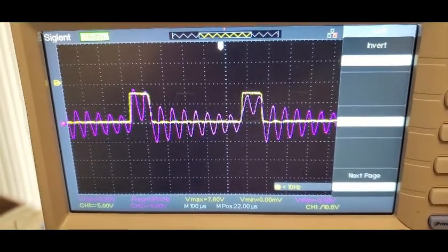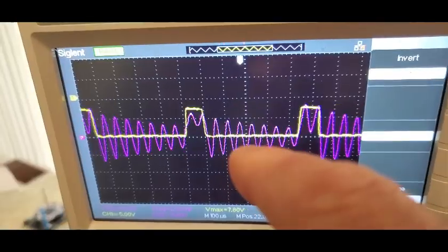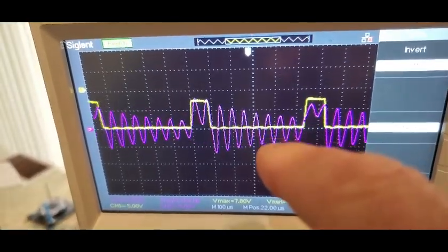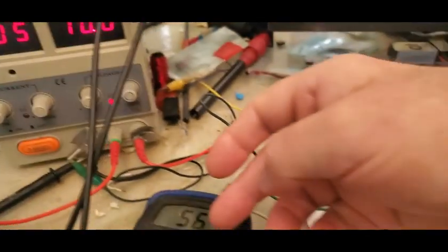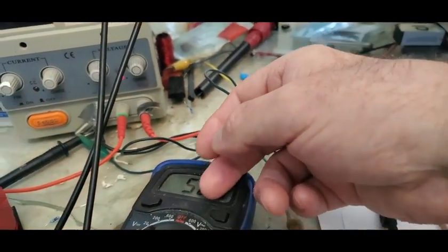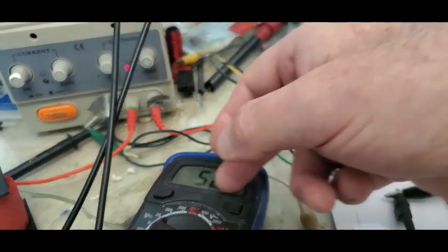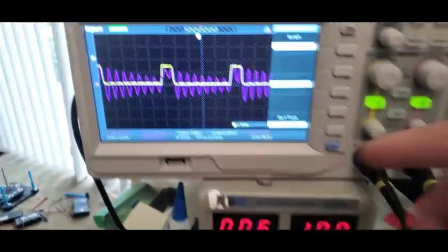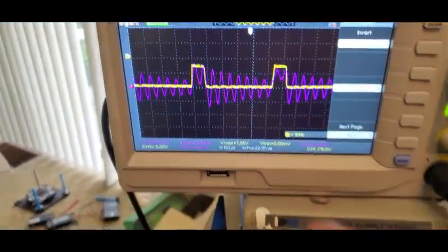Yeah, 35. We're at 30. Can we get to 25? Yeah, we can even get to 25. If I go any faster, it's just not going to turn on. But you can see it's starting to get the larger oscillations, and all this time we've trended downward from close to 100 milliamps down to 50 milliamps. And this oscillation is happening essentially independent of that.